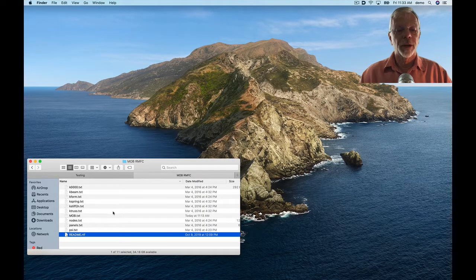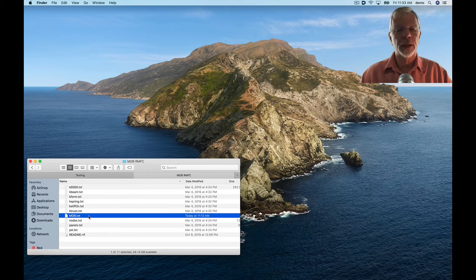There are a lot of files here, and most of them are associated with different ways of modeling the connectors. We'll get to that in a minute, but first, the file we need to run is mob.txt, and what this file does is it just generates the added mass, hydrodynamic damping, and wave exciting forces for the 5-module MOB.